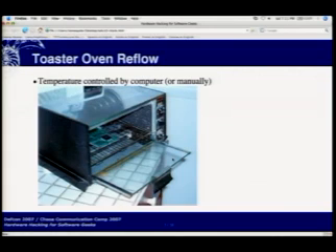The one place that it would fail is a double-sided surface mount board like these. If you were to throw this in the oven to try to solder something on the side with the batteries, you would lose all your LEDs and be saddened.